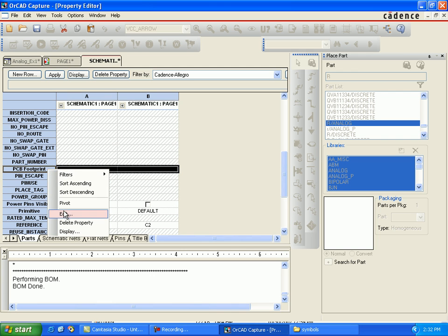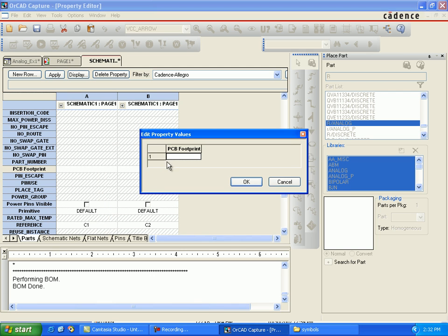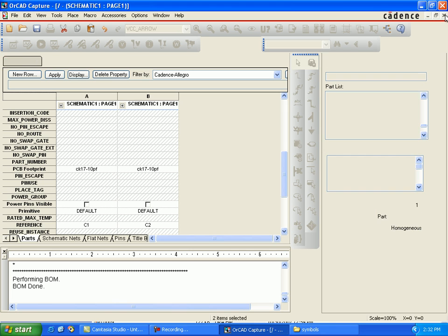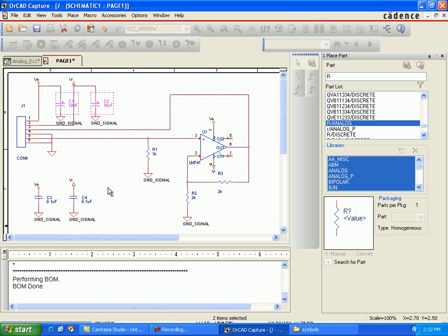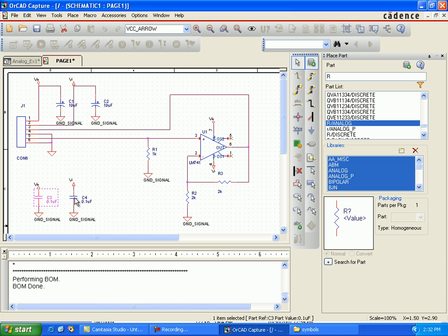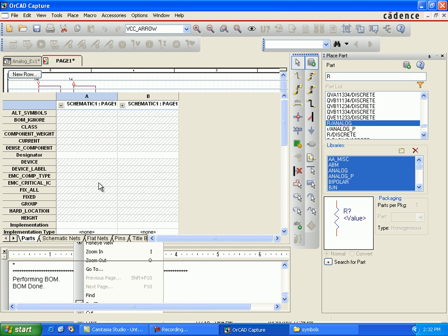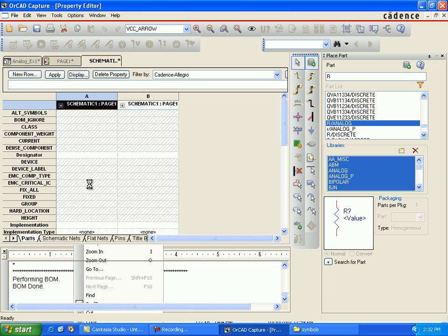This will connect the components C1 and C2 to what dimension they are, what value they are, what type they are, what material. Already made files you have to download from the internet, or you will have them in your particular folder as shown. Right, in the PCB footprint, click that. Same for these two ground capacitors C3, C4, they are SMD surface mount capacitors.